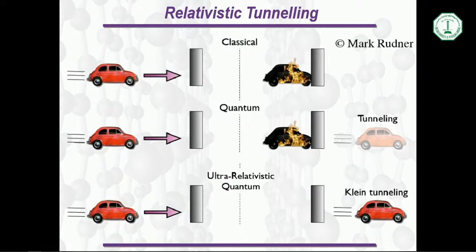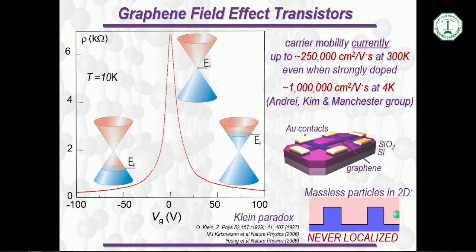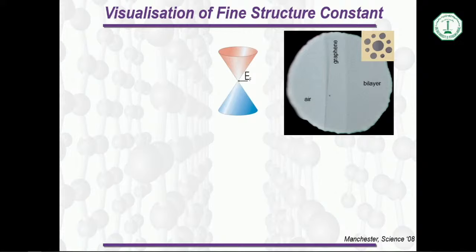So in material science, the structure of a material immediately gets reflected in its unique properties, and then it gives rise to very high mobility. So electrons move very fast. So it's very good for transistor application. It's very good for high frequency applications, and also optical properties of graphene. You can ask me, so what kind of optical properties can you expect? It's only one atom thick. It actually absorbs quite a large fraction of light, maybe about 2.3%.